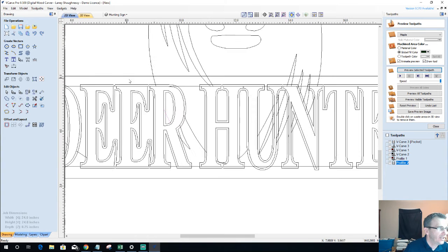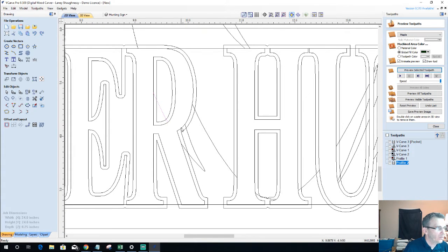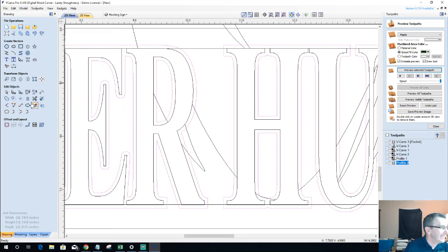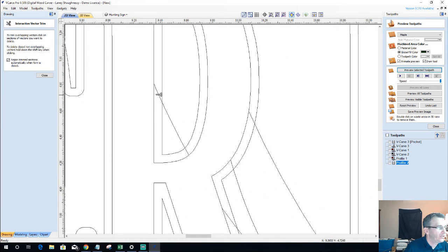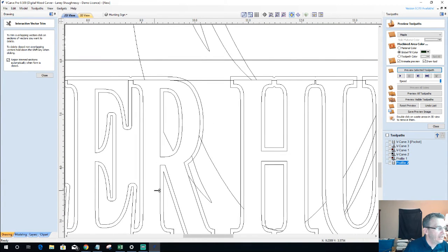This gives us a chance to figure out how we would troubleshoot this. So how would we do this? I want to close off this vector. So what I'm going to do is use my boundary as some trimming lines. So I'm going to ungroup that, and I'm going to go into start interactively trimming. First thing I'm going to do is come in here and trim this line away, and that. That'll create that inner area, which is eventually going to get deleted here in a moment anyway.